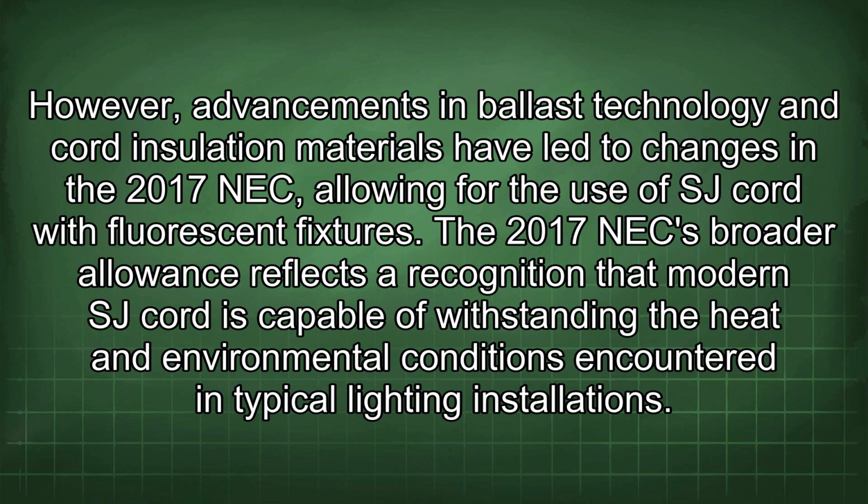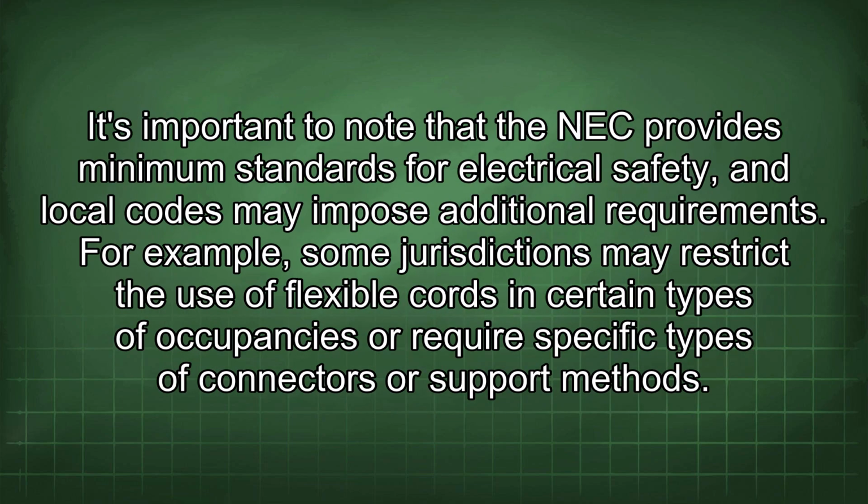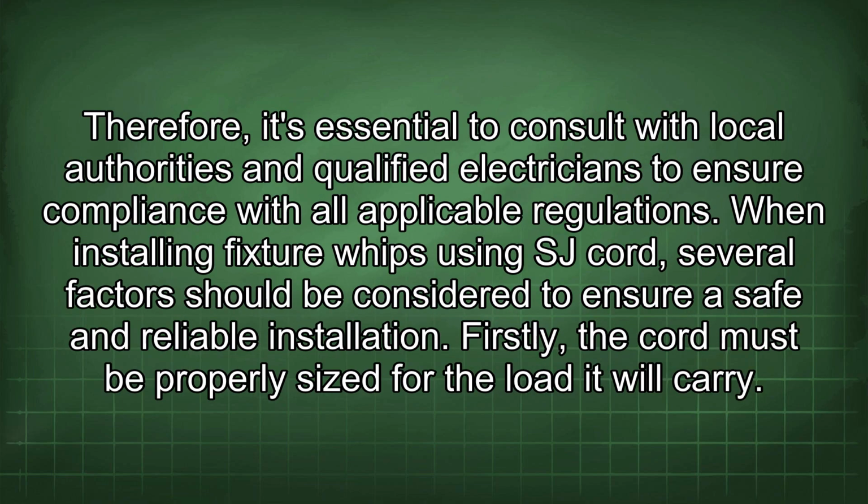The 2017 NEC's broader allowance reflects a recognition that modern SJ cord is capable of withstanding the heat and environmental conditions encountered in typical lighting installations. It's important to note that the NEC provides minimum standards for electrical safety, and local codes may impose additional requirements. For example, some jurisdictions may restrict the use of flexible cords in certain types of occupancies or require specific types of connectors or support methods. Therefore, it's essential to consult with local authorities and qualified electricians to ensure compliance with all applicable regulations.